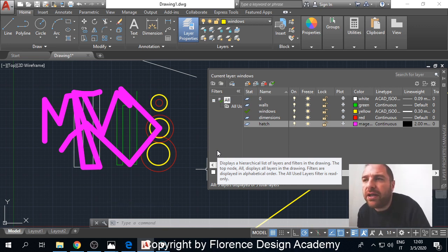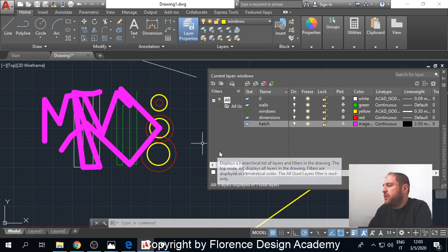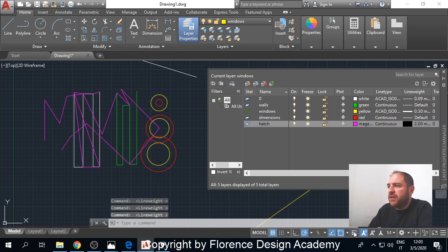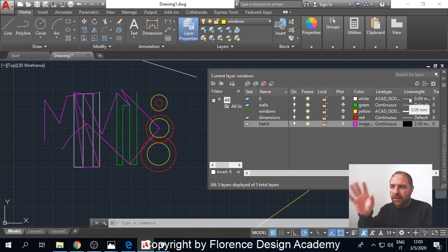And this is happening only because this tiny button that I have placed in my interface, called the line weight display, has been enabled. With this gray, even if I have all my different line weights, believe it or not, I will never see line weights on screen.